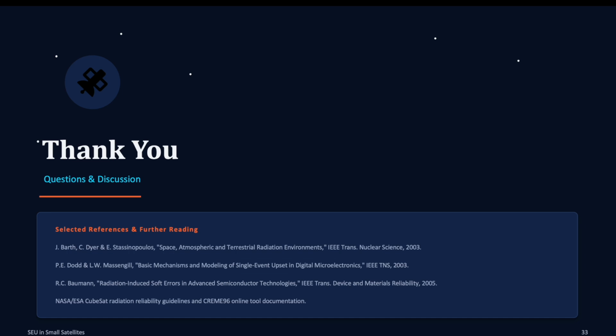Okay, thank you. But it is important, I think, the damage to the MOSFETs, that's the EPS-related damage, right? We might observe single event burnouts on those higher orbits. Those are hard to recover. You need to have a physical backup. So there's no other way. Okay, any other questions?